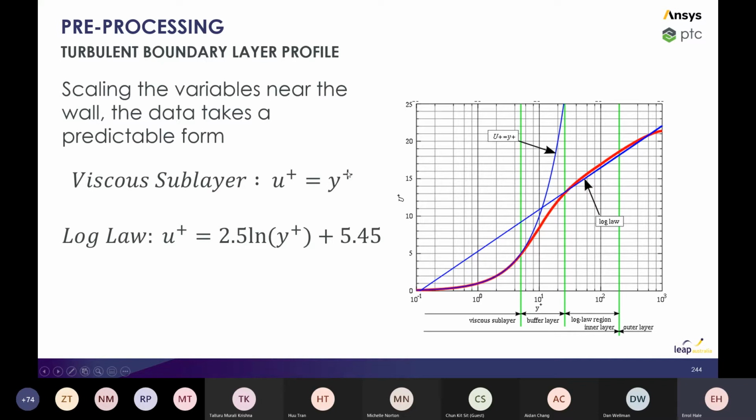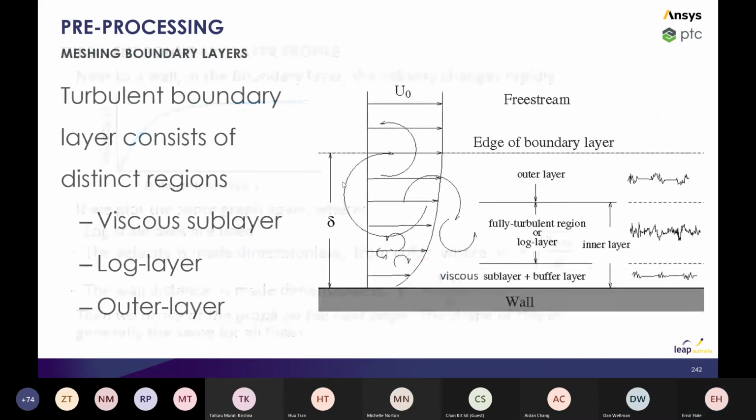Okay, this is really important because there are different things happening at the different layers. The viscous sublayer, sometimes called the laminar sublayer, which gives you an indication of what's happening. It's usually quite laminar flow. Our transition layer is the transition between the viscous and the log law layer.